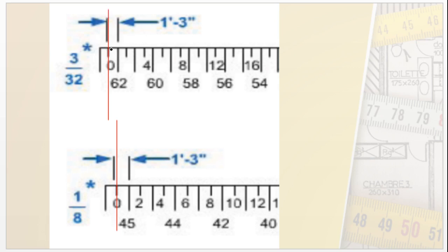So we can say this is 1, and the extended portion over there will be approximately 25%. From the figure you can say that will be 1 foot 3 inch. In case of this as well, this is 1 foot, and we can divide this into 12 portions, and take 3 of that, or we can divide into 4 divisions and 1 of that division will denote 3 inch. So in total this will be 1 foot 3 inch.